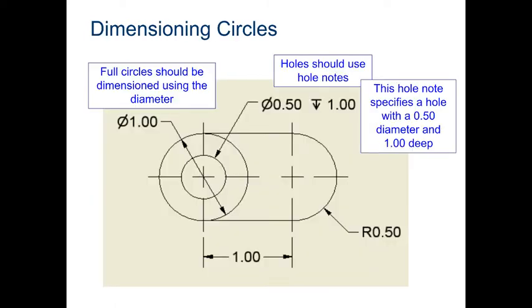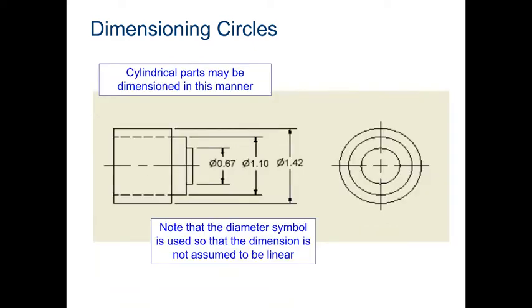So, dimensioning circles, we talked about this before. This is the diameter of an object. The arcs or the curves, 3-point arcs, all that kind of stuff, those are radiuses. These are full circles. When you have a full circle, you use diameter to identify those things. We've talked about this before. Nothing new. This is a new way of dimensioning diameters as well. I told you before, you have to do it from the center where the circle is actually facing you. You don't have to do it that way anymore. You can use, and is this unidirectional or is this aligned?